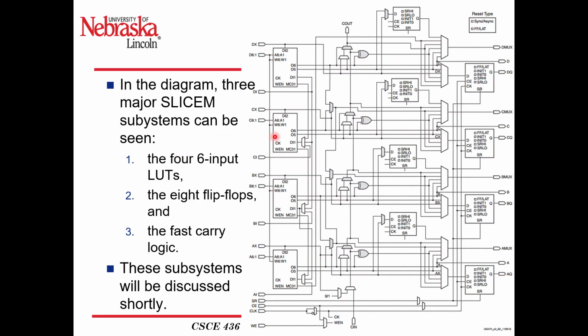So it's 64 bits. How many bits do you need to address each of these 64 rows, 64 by 1 RAMs? So it's a lookup table. You need 6 bits of address to be able to address each of those values. So we have address lines coming in to address each of those rows in the lookup table to be able to actually implement different functions.